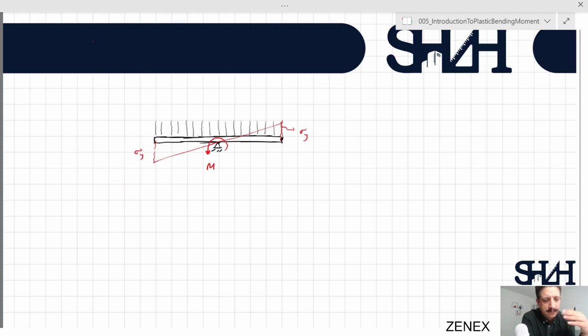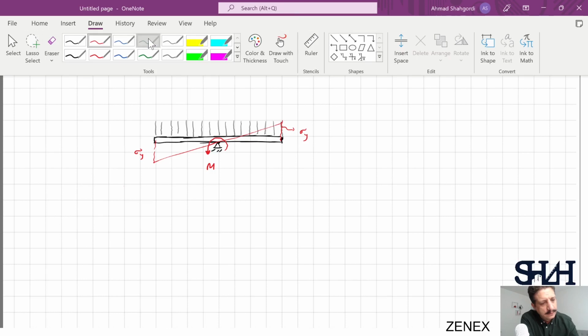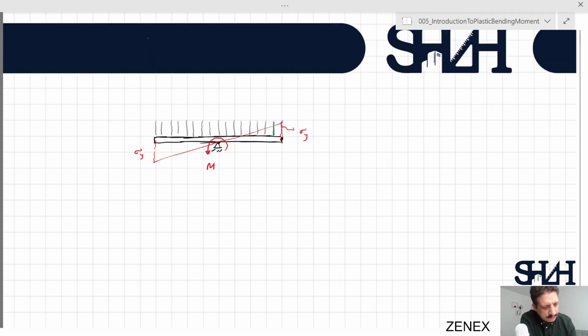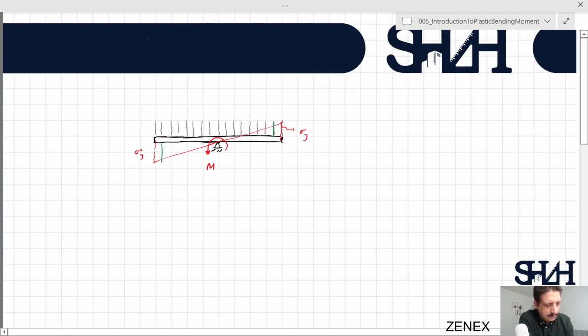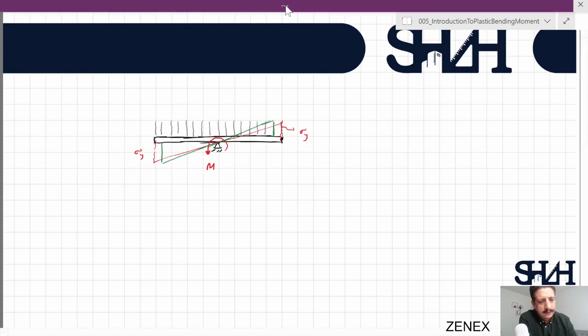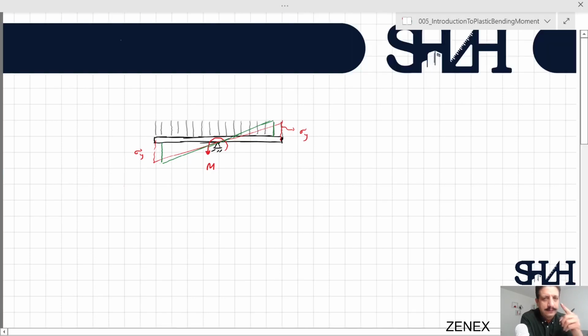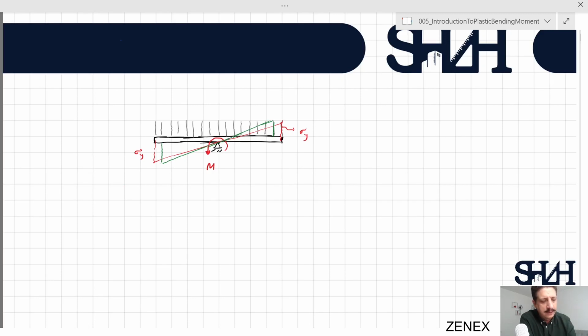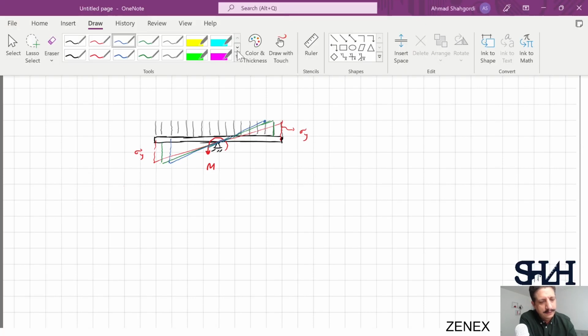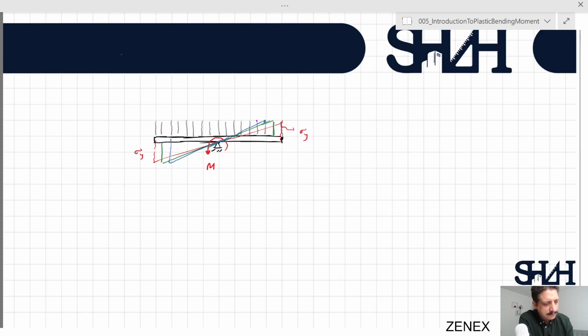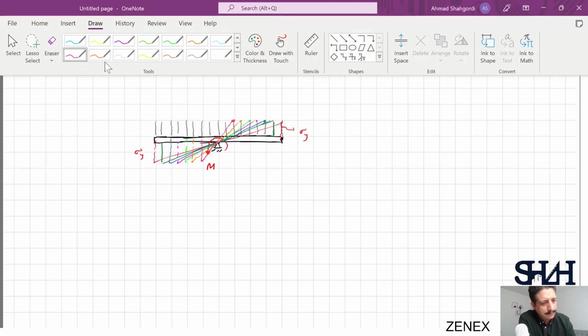We calculated the same example with 3 rods on each side. Then you can increase the moment until the next rod yields. So the next phase is we increase the load so that the next element will yield, and then we can increase the moment. The second furthest elements are now plastic. The stress in those elements cannot be increased. Now it goes to the next one, and the next one, and so on, until very close to the center.